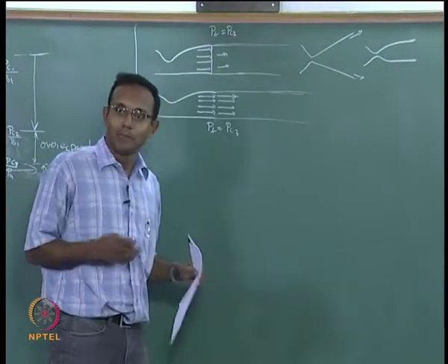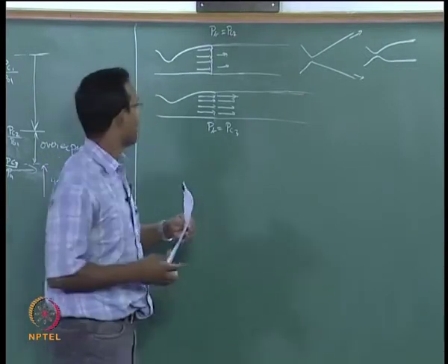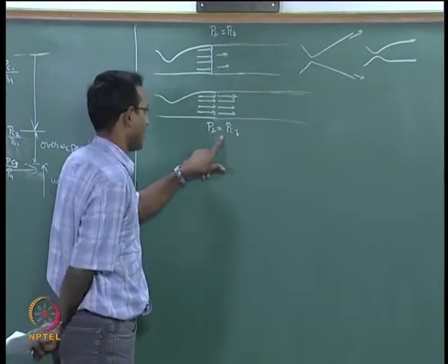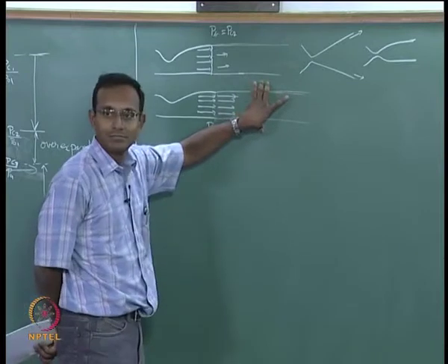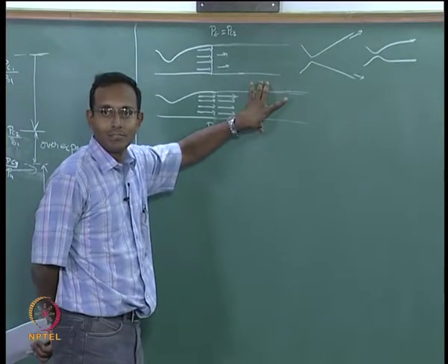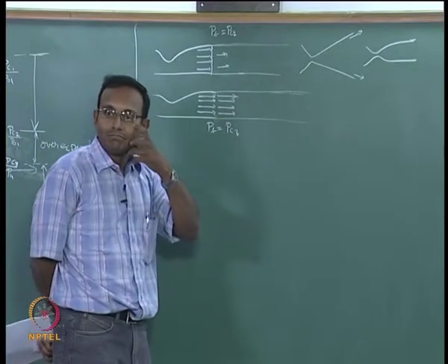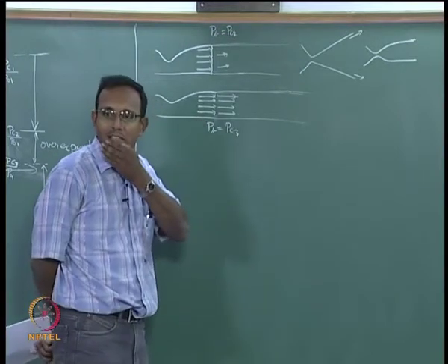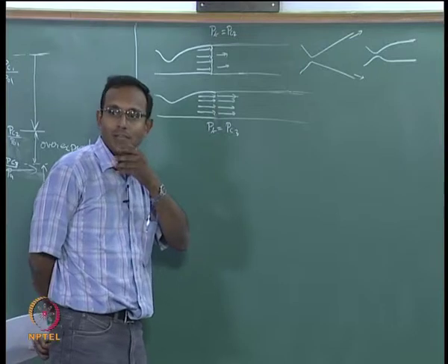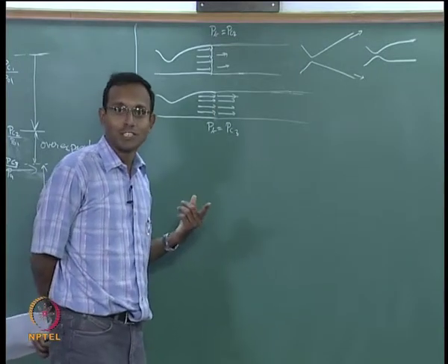If I think about the simplest thing, say I am very close to this P critical 3 and I am increasing my pressure here slightly, what kind of shock should I have at the exit? Only thing possible is oblique shock. There is no other choice for you.